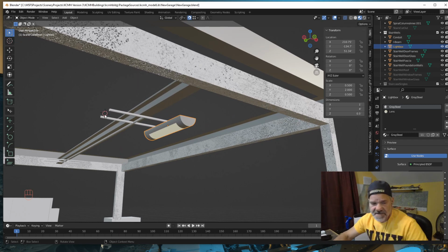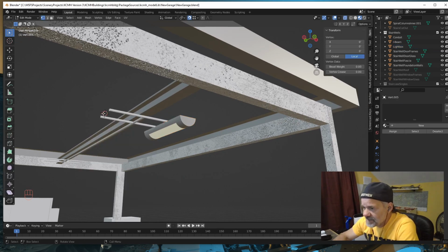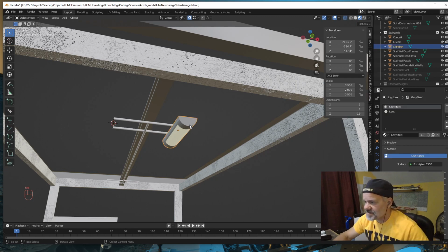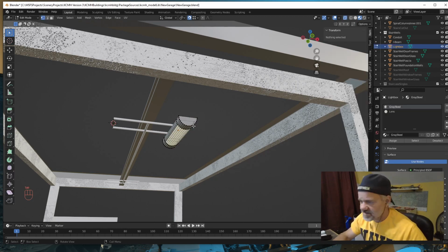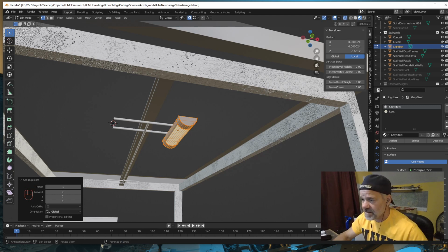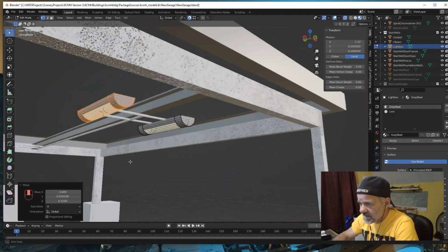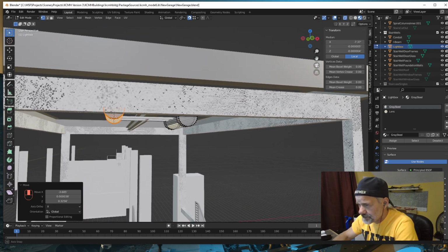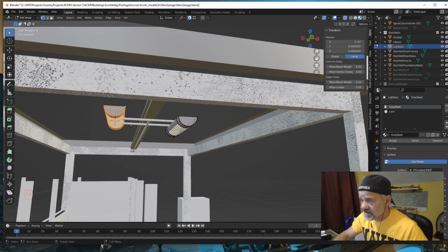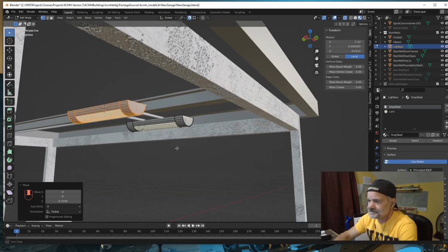All right, so with the 3D cursor there, I'm going to Shift A and add a single vertex. So now I have a vertex right there. Now I'm going to get out of edit mode, select our light, go into edit mode, select all, Shift D, escape, and then G. There we go. We might need to move that down. So with those selected, Shift select this vertex so we have an active vertex, and then G, Z, even with this one. There. All right.